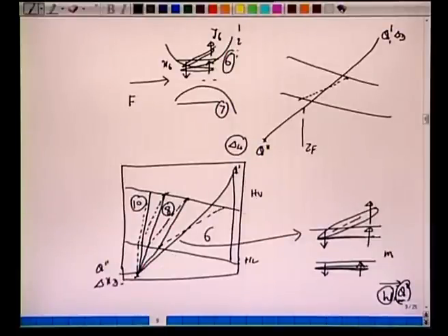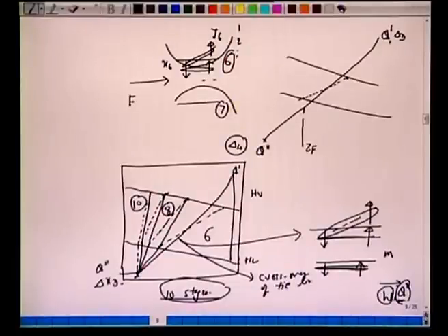All right. So how many plates are required? If we do it carefully, we require 10 stages. See, there is a crossover at this point. There is a crossover of the tie line, and it's very important that we mark this point. That's the location of the feed. The feed enters just after the 6 stages which we have completed.